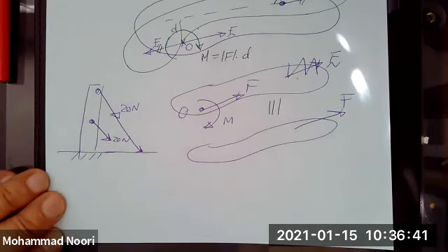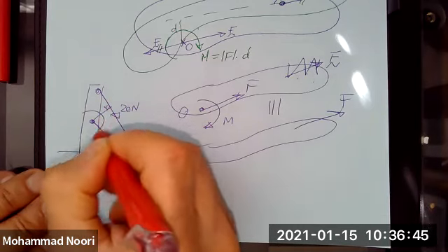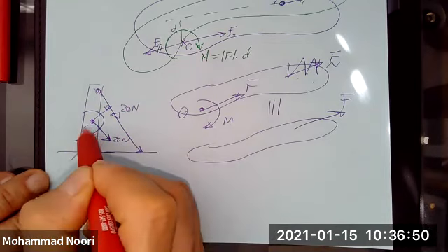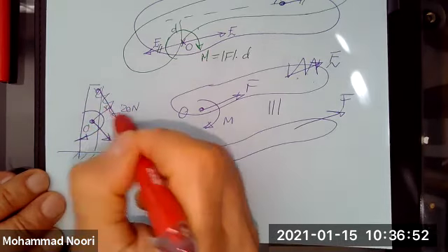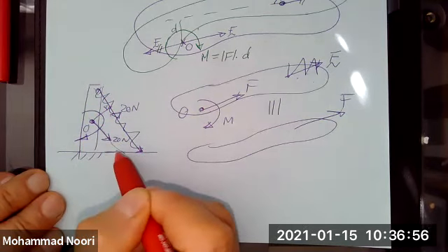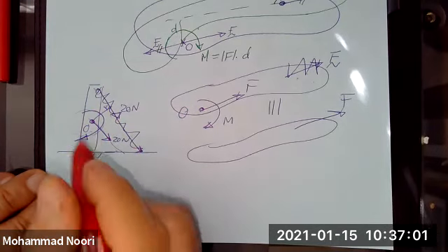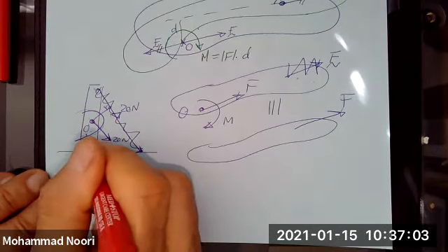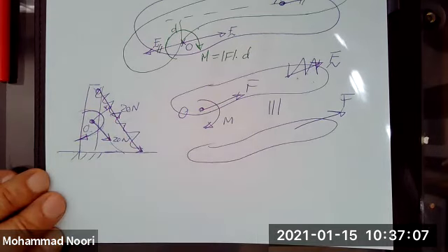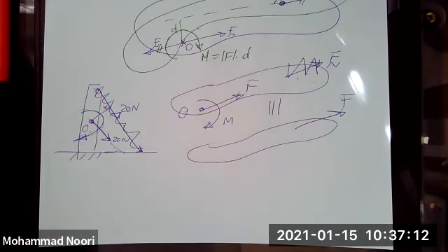You can, as long as you add a moment, which is the moment that this force generates about this new location. In other words, you can cut this out, put a rope here that exerts the same force, but you need also maybe a torsional spring of some sort that generates a moment, which is the moment of that force about that point. We call these equivalent systems, okay?